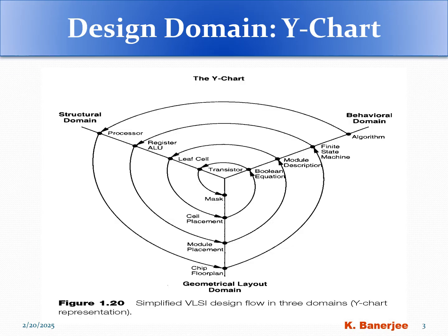Okay, so the next topic I will discuss is design domain, and this one is another very important topic from your semester perspective. This is known as the Y chart as well. Gajski's Y chart. So we have 3 domains here: structural domain, behavioral domain, and the last one is geometric layout domain or physical domain. So the VLSI design process is described in these 3 domains, and these axes are actually shown like a Y, and that is why this chart is known as the Y chart.